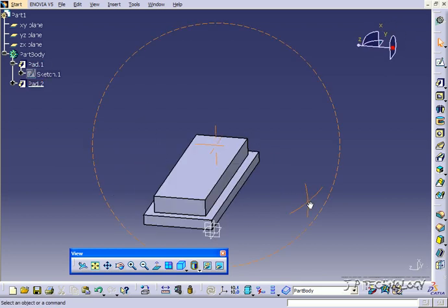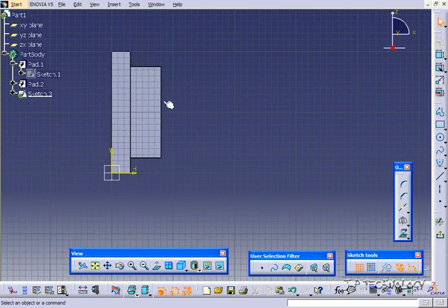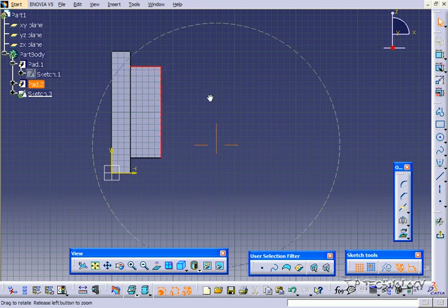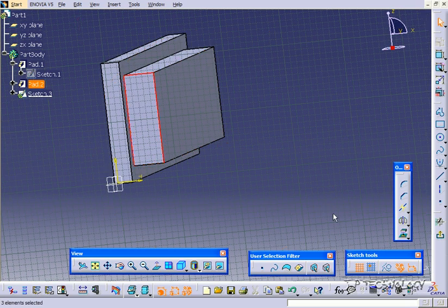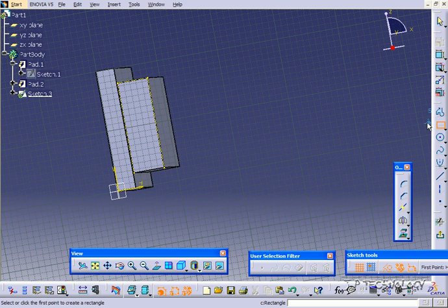So first off, we're going to make the profile. Let's click this face here, click Sketch, and let's click the top line here, press Control, click this line here, and this line here, select them all, project them out, and turn them all into construction elements. Now we'll click the rectangle, and let's draw a rectangle in here. Now I'm just going to go back because I had it selected as the construction, so remember to turn it off. Now we'll do another rectangle.